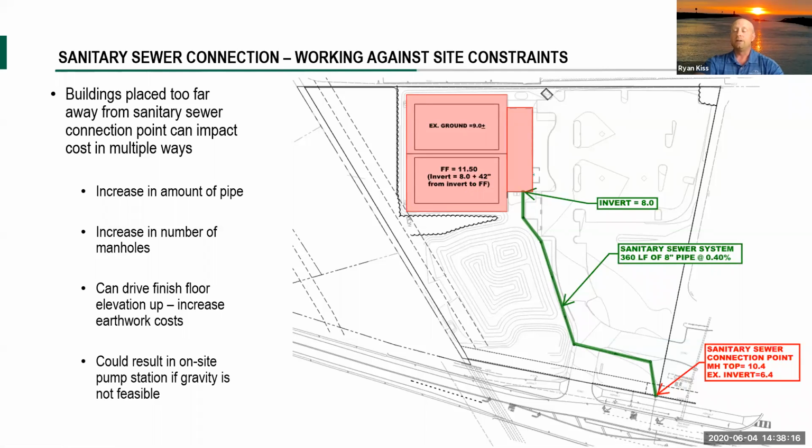So many times we'll reach out to an architect very early in the project, and oftentimes we're finding it's even before MEP has been signed up or has started doing their work. We're asking, hey, do you know where the sanitary sewer exits the building? And do we know what the minimum depth of sewer connection below finished floor is?